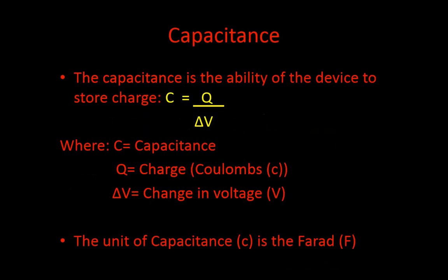So our capacitance, the ability of the device to store charge, is given by this simple equation: C is equal to Q over V, the potential difference across the plates. Capacitance is in the unit of farads, and the farad is one of those large units, so you'll often see 10 to the negative 6, 10 to the negative 9 farads in the examples we will look at. Q, of course, is in coulombs, which confusingly is another C that you will see in your calculations. So don't confuse coulombs of charge with C for capacitance. And finally, voltage, or potential difference, which is given in volts.